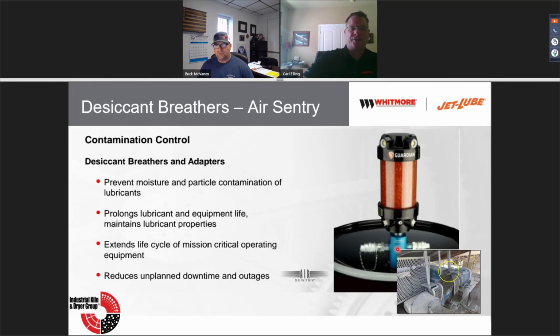So if you put this on a gearbox or hydraulic reservoir, and it's expanding and exhausting, well, in our patented desiccant breather there's basically a silicone cover here that will plug this up where air cannot go back up in here, and this is where your money's being spent, the desiccant breather here. So these will open up, and the air will exhaust. As this is exhausting, it'll come right out through here. They've got 4 of them to come through. They can handle up to 750 CFM, which is quite extensive. Intake-wise, it can handle about 25 CFM.